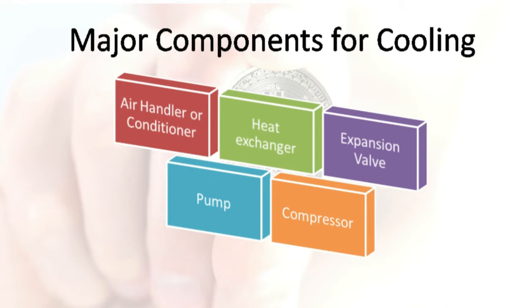The expansion valve eliminates pressure from the liquid coolant to allow the evaporator to shift its state from a liquid to a vapor. Although the liquid refrigerant exiting the expansion valve is cold, the high pressure liquid refrigerant entering the expansion valve will be hot. Inside the valve, the orifice does not expel heat, but rather it lowers the pressure.